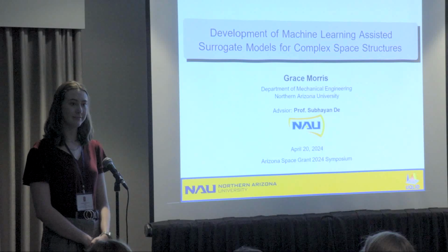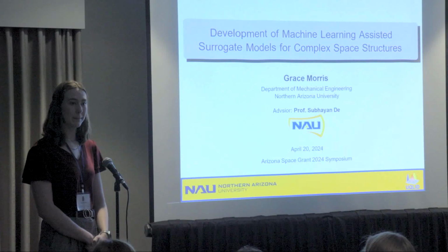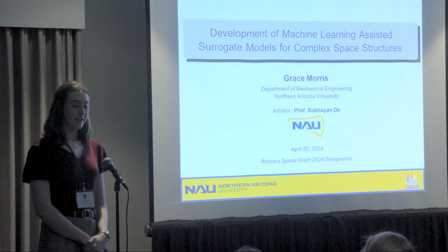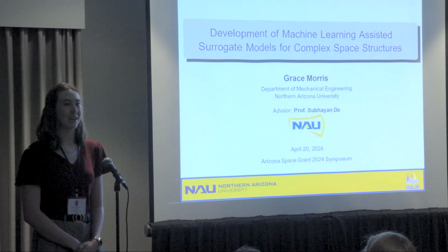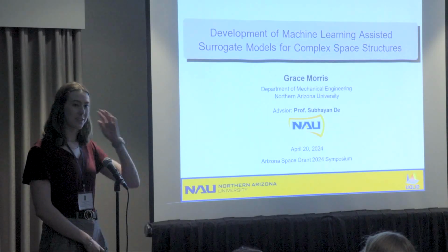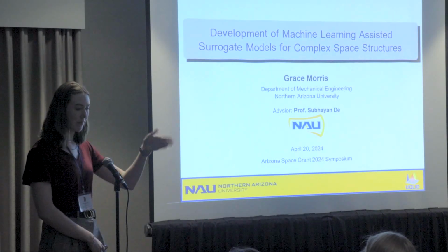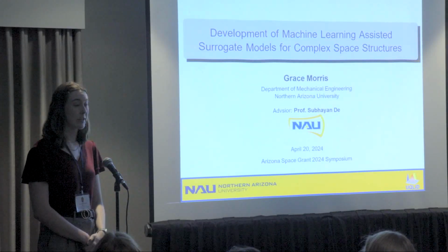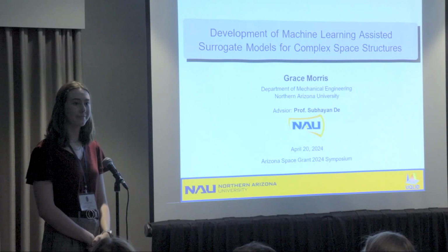So is there any reason you chose to rotate a lot of components on the board rather than just say, okay, take my ADC and 45 degrees? The main issue was routing. I don't know if you saw the ADC. It has 48 pins, and it's about 1 centimeter by 1 centimeter. So it's pretty hard routing. It was easier to have that be straight up and down and then rotate everything else because it was pretty simple. We definitely could do that for the next iterations, though.